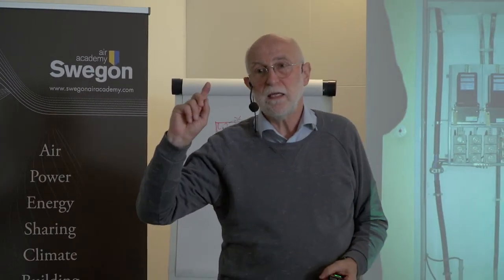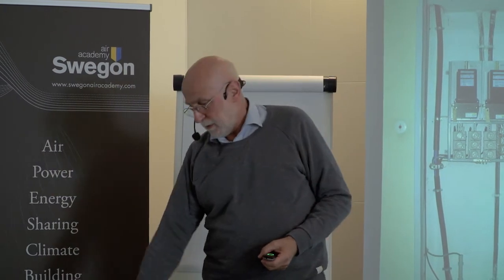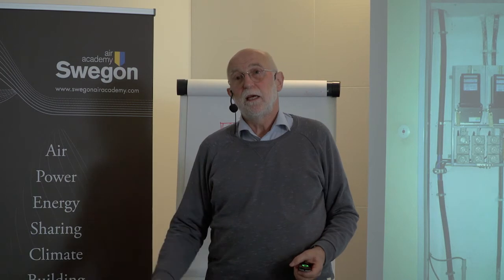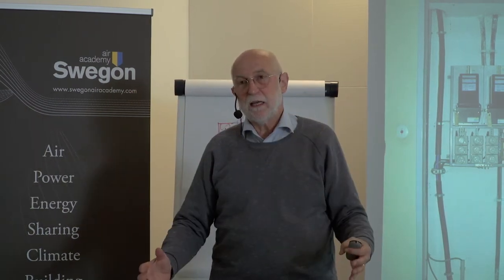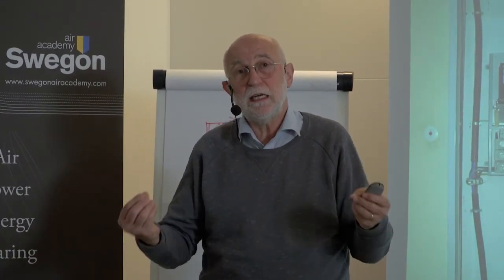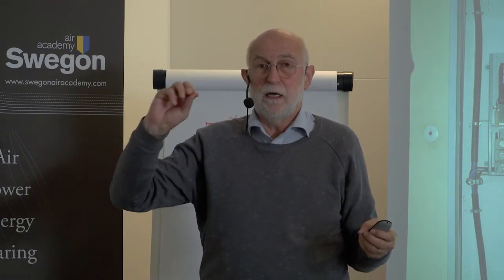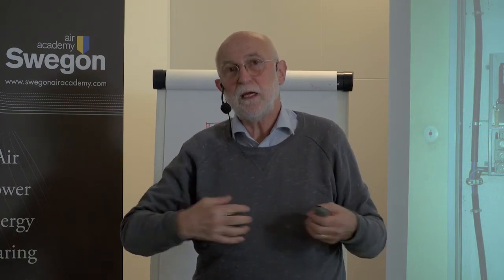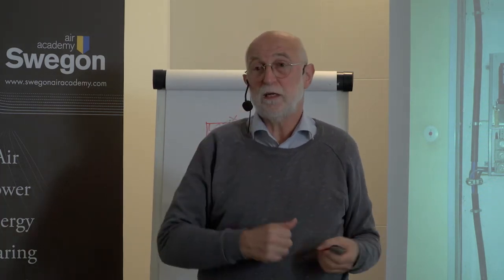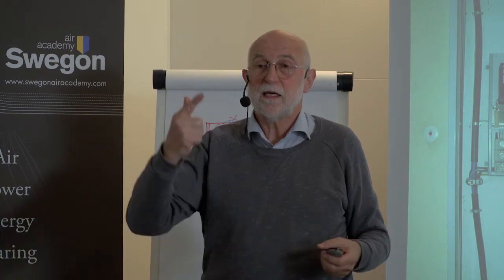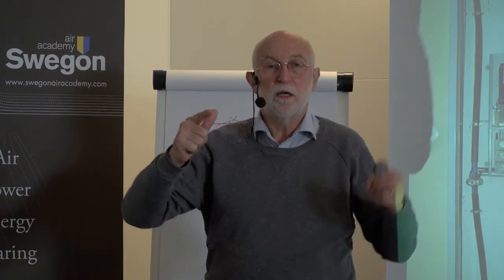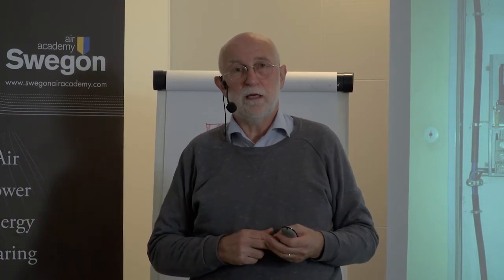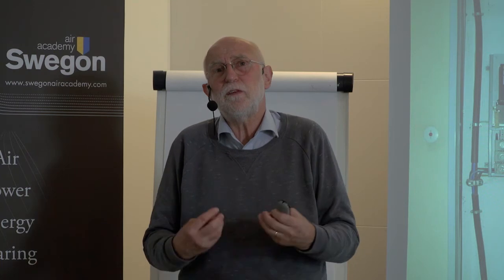So our idea was, forget about this floor heating because they were rotten and we couldn't go on with it. If we make a building shell which is so good that we can heat it with the air, but not with a lot of air, just the air we need anyway for our health, 20, 30 cubic meters per hour. And second, the air shouldn't be too hot, not more than 50, 55 degrees, to have no discomfort. And with this, you can transport very little air.